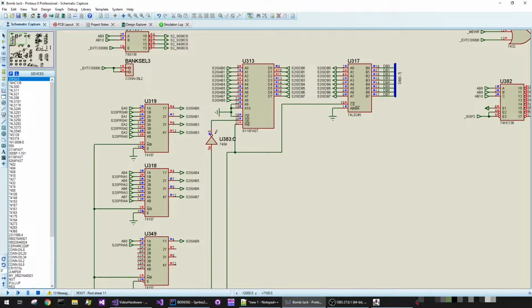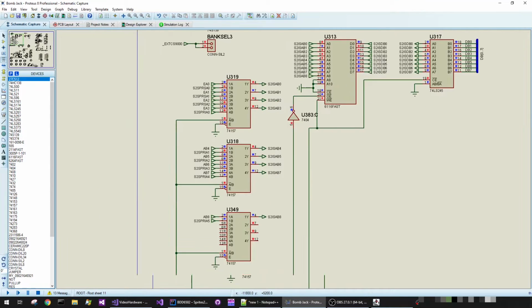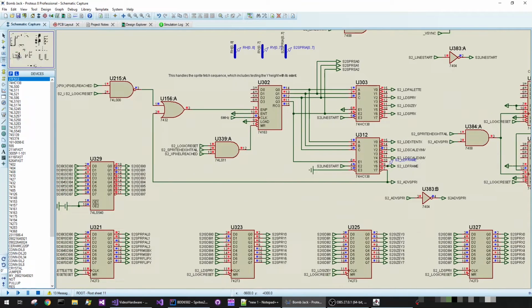Doing it for this means that when it's not writing values, it's reading the sprite registers and accessing them. There's a little bit of bus direction logic here, so that I can say, for example, write a value from the external data bus or read a value to the internal data bus here. And this logic down here is all to do with managing the internal sprite state.